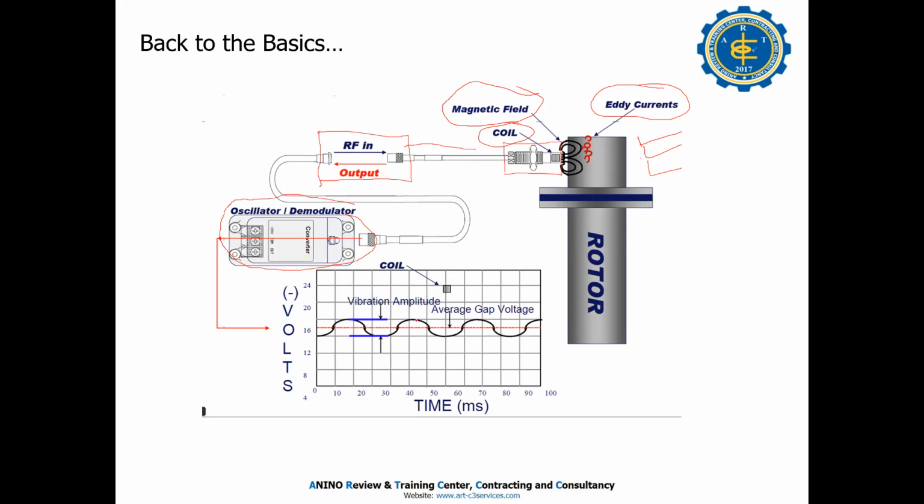So in our System 1, we have three kinds of proximity probe. The first is the radial, which is 7 to 8 volts. Also radial, we have 3 volts. And then the third, the axial, we have negative 10 volts. Always negative.